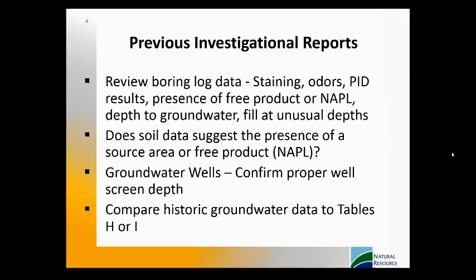When reviewing boring logs, there's a lot of important information provided. All this site data will be used to incorporate and update your conceptual site model. You see those listed for the boring logs, some of the details that can be inferred or obtained from them. One thing I want to point out is fill at unusual depths. Most likely that might be a man-made pathway or corridor, something you want to pay attention to, because soil gas can migrate along those corridors.